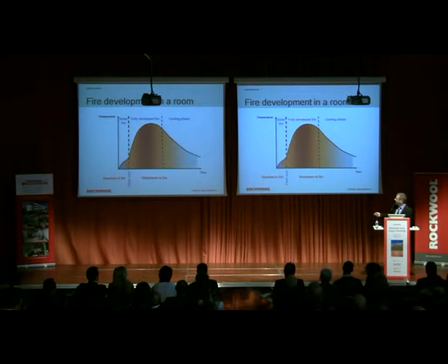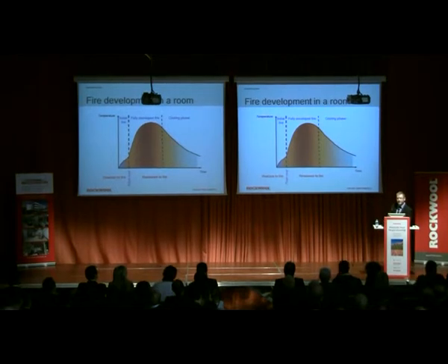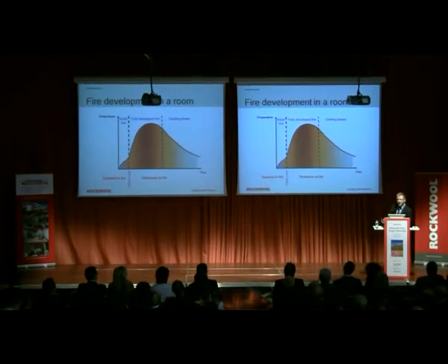So here in this part, we are concerned with reaction to fire testing, and we are measuring both materials or constructions, but using a small fire exposure and measuring things on the fire side. But now, when we pass the flashover stage, what we are concerned about is resistance of constructions to fire, and we are not concerned about what happens on the fire side because everything is in fire. But what happens on the other side, are people safe on the other side?